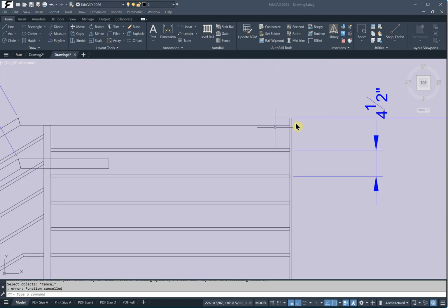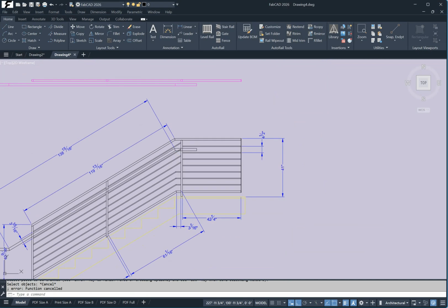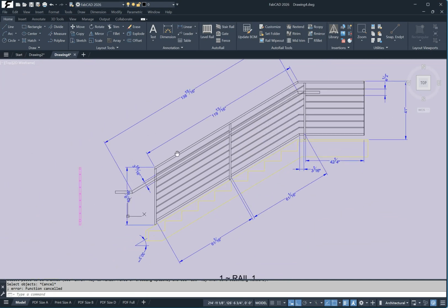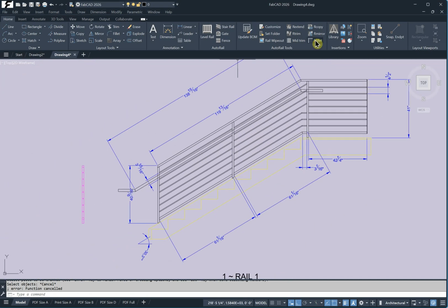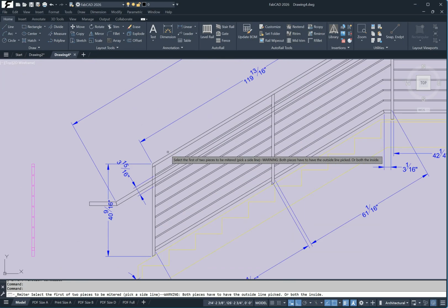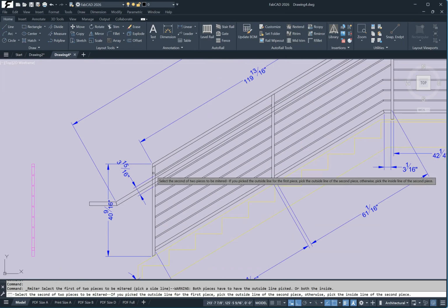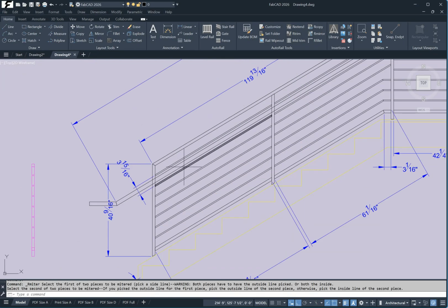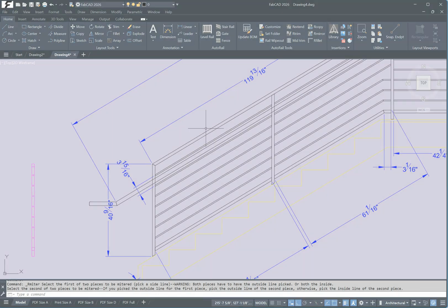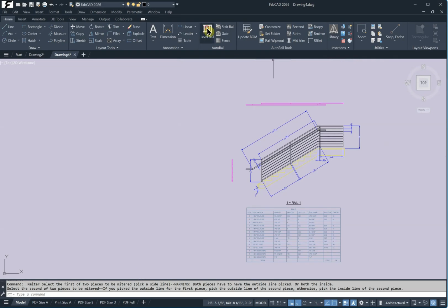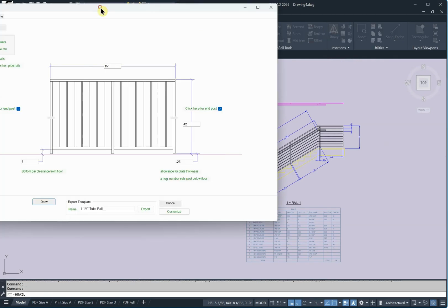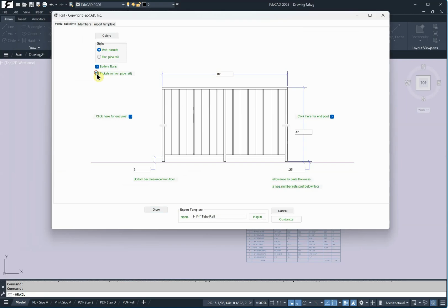Where the strap is, of course, it's a butt joint because you don't want to miter that, but maybe you want to miter the bottom. So that's where the rail fillet comes in handy again. I just do rail fillet and I pick this here and this here and it changes a butt joint to a miter joint. In the horizontal rail program, we've added options.